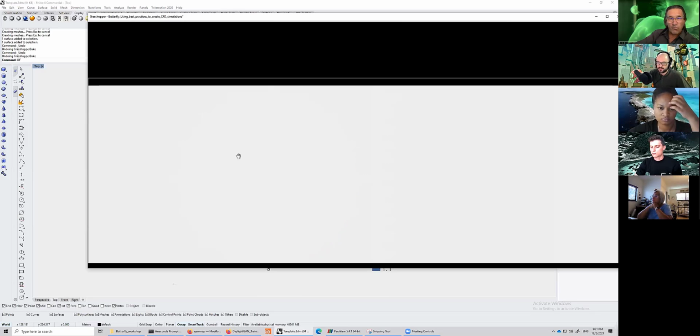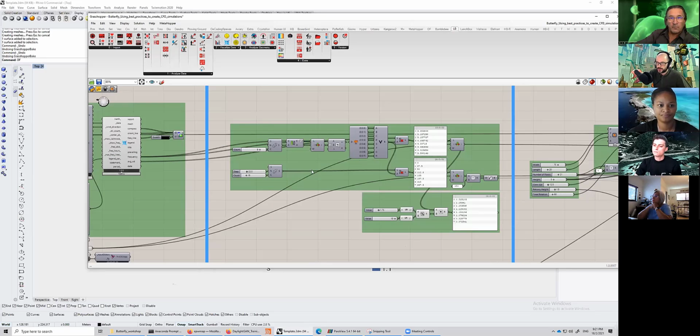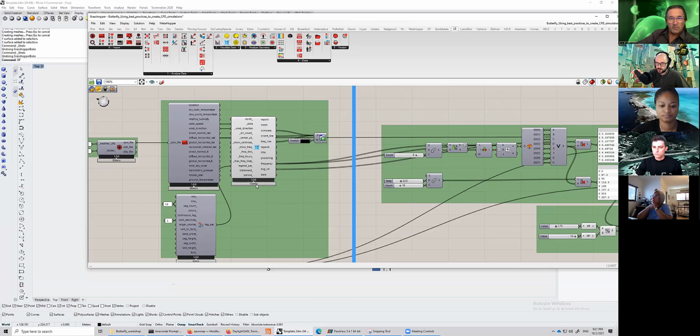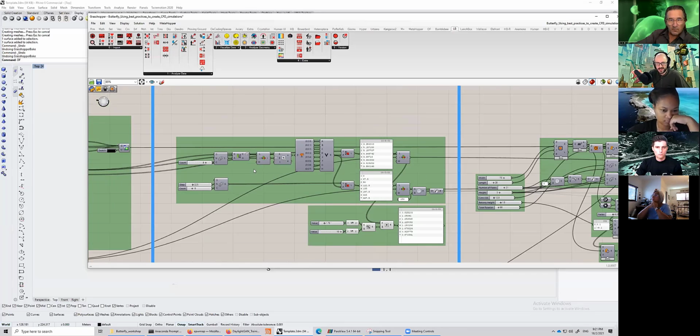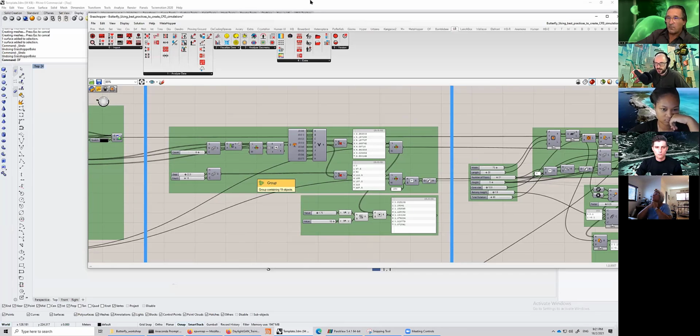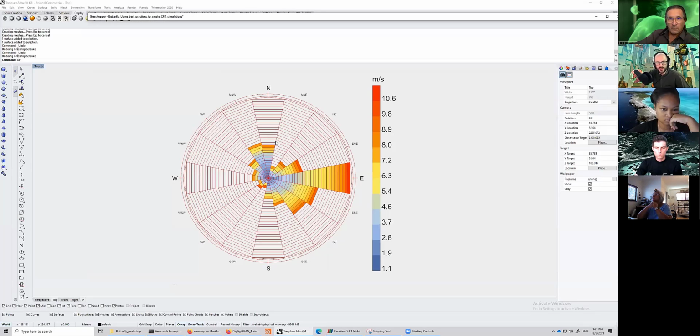Okay, and how do we make use of this? When you actually run a CFD simulation, you don't really run one, right? You run multiple of them, and you select the dominant wind directions. How many is not very clear, right? It depends on the scope of your study, the time you have, the money you have, the computational resources. In the real world, it will be almost defined by others than you, right? But usually I would say I would never do less than 6, a rule of thumb, and usually you can go all the way up to 16. The most I've done is 36 wind directions, which I think is an overkill. We did it because it sounded nice.